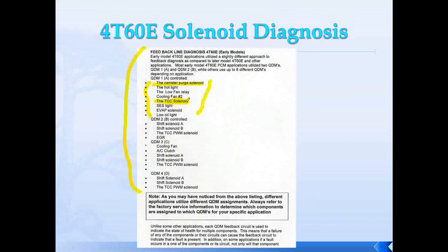Your diagnostics will give you that. So go to the diagnostic routines themselves. It will tell you what's actually on that driver circuit to help you isolate what could cause your component failure. So again, just a little tidbit for you there. It looks pretty confusing. It really is not. The big thing you need to keep in mind here is the reason your component may not be working may not be due just strictly to the component that you're dealing with that's not working.